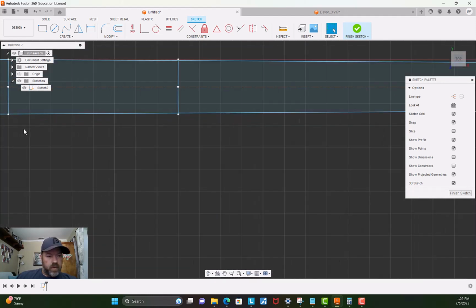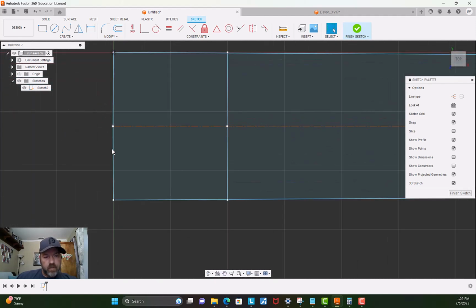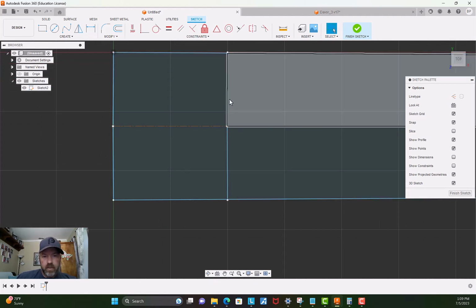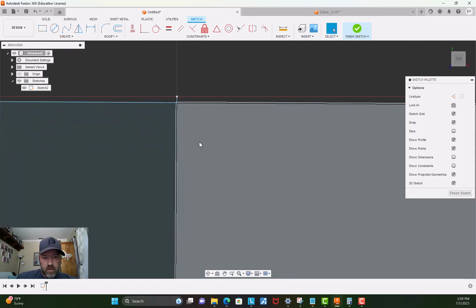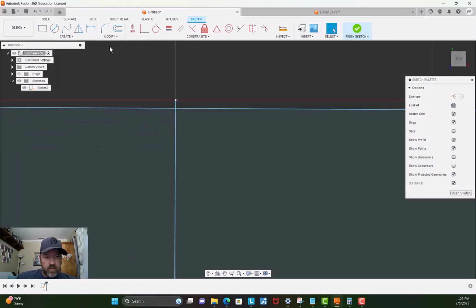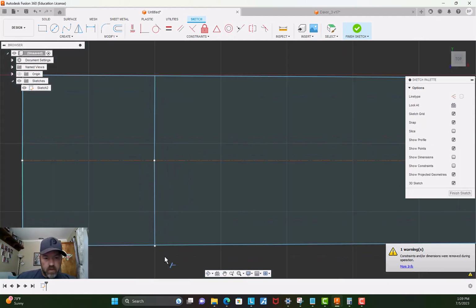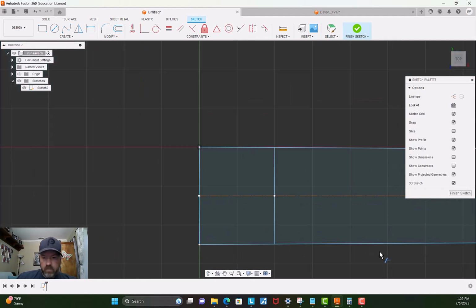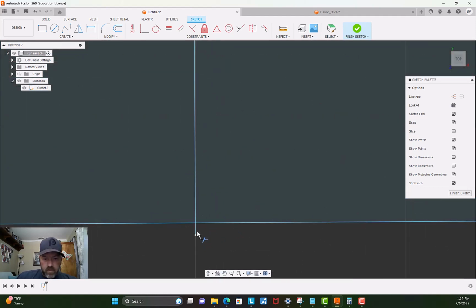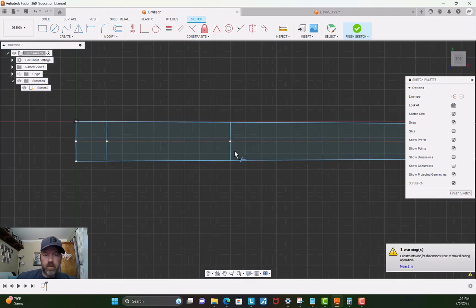Oh, one thing that I forgot to mention is we need to do the opposite when we copy from the large end moving to the right, because it will actually extend over the profile. As you can see here, if we zoom in, this extends up. So we can again go to Modify, Trim. We can trim this off here. We'll do the same in the bottom. And we can do the same for this guy. Okay.